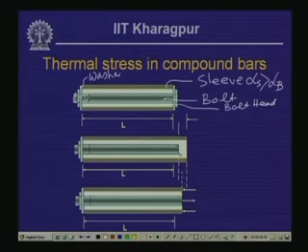So, in the second figure as shown, we have removed the bolt head and allowed the whole system to expand freely. Since the thermal expansion coefficient of the outer sleeve is larger than that of the bolt inside, it is expected that the outer sleeve will undergo more expansion than the central bolt, and since it is free to move, it has expanded.